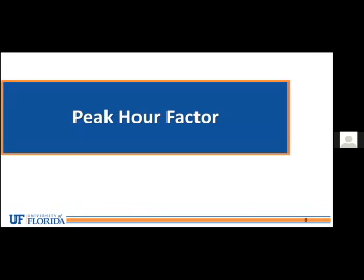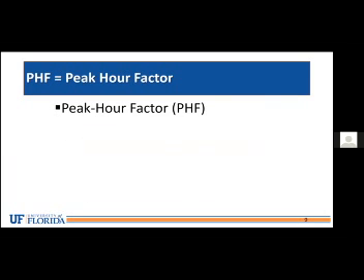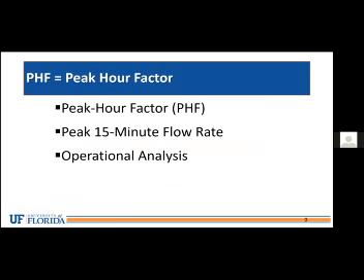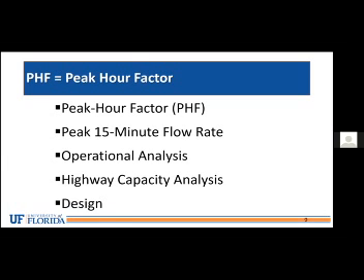One of the other things we'll talk about is the peak hour factor. It is a very important factor in traffic engineering. It is something that is certainly needed if you're doing highway capacity analysis. You're looking at the peak 15-minute flow rate, but if you're doing any type of highway capacity analysis, it's an important factor that many people often overlook. It's something you certainly do need to look at if you're doing highway capacity analysis or in design.